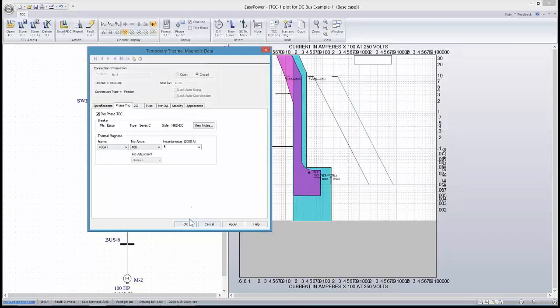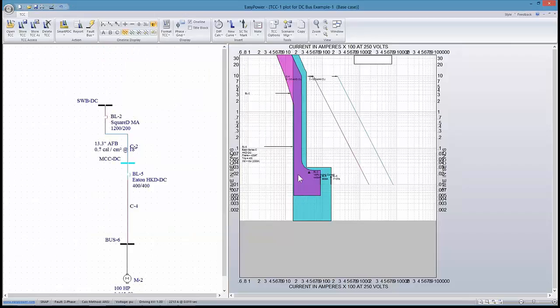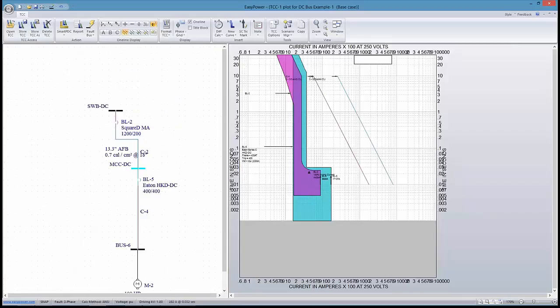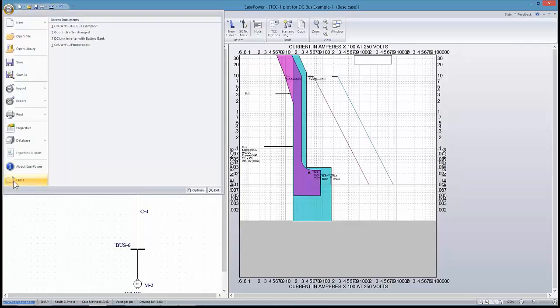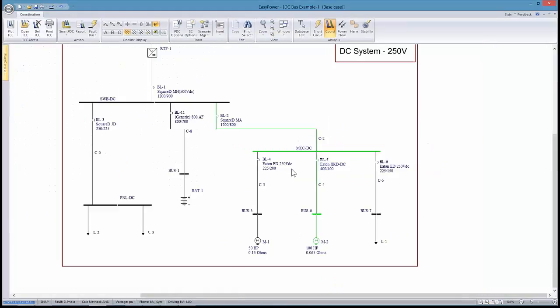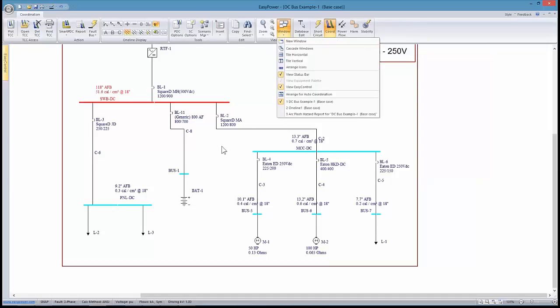All right. The point that I'm trying to make is that at this particular setup, it looks like we have miscoordinated breakers, and yet, because the trip currents are offset by enough that this breaker will protect, trip and isolate this motor, and this breaker will trip a little bit less but could simultaneously trip, it means we might have coordination problems. But when we go back to the overall system now and fault the buses, you can see that we have incident energies that reflect the protective device.